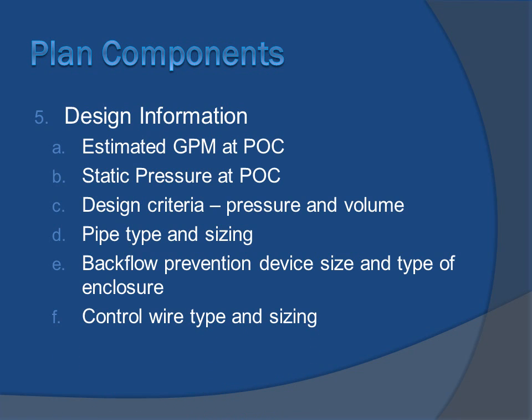Control wire type and sizing. I like the multi-strand wire. It's like 5 or 6, sometimes 8 wires bundled together with black tubing around it. You've got it all connected there. It's more expensive than using the single wires, but usually that's red and white, and it's a lot easier when it's color coded to know zone 1's yellow, zone.